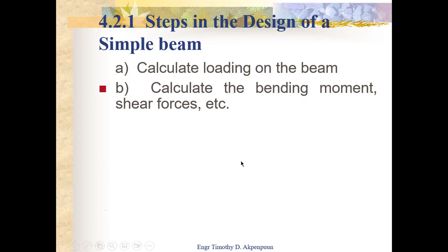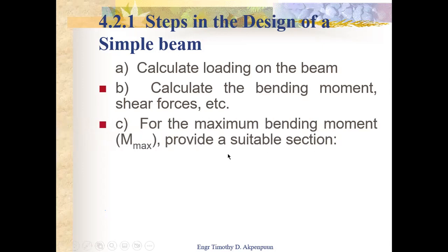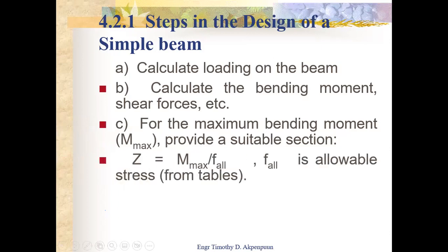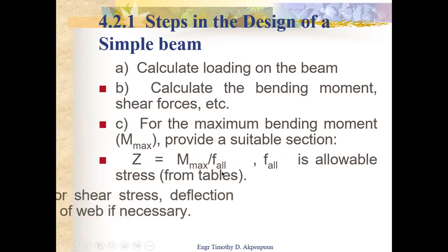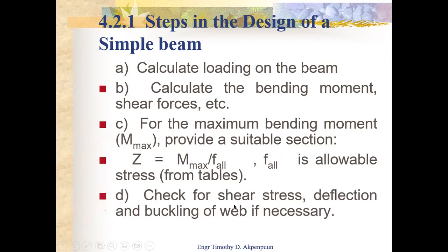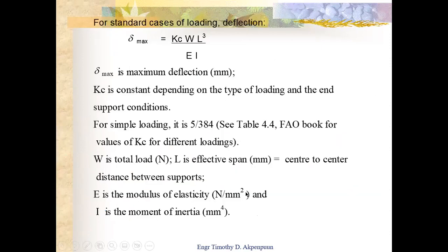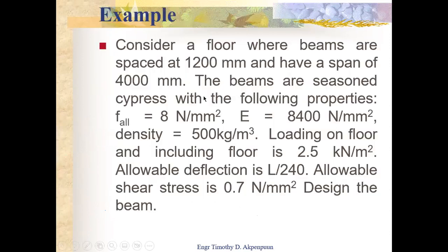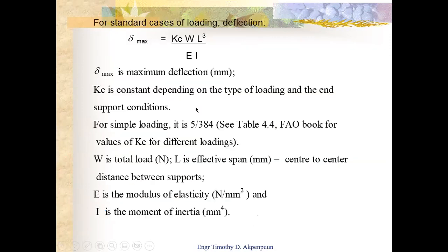Number B, calculate the bending and shear forces. C, for the maximum bending moment, provide a suitable section. This is it. Check for shear stress, deflection, and buckling. And buckling of web, forget about buckling of web, if necessary. Very good. And then this for deflection.